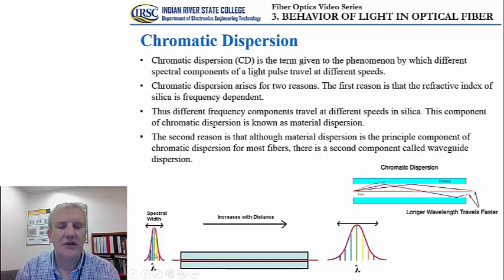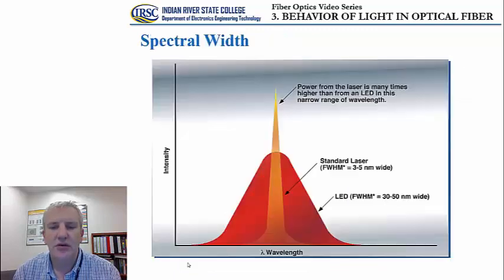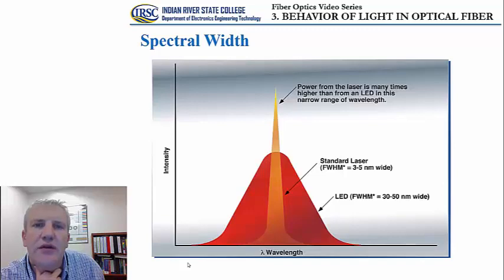And we see that each of these different wavelengths will be propagating along the core of the optical fiber at different velocities, thus causing the time delays on the other side of the optical fiber and ultimately spread of the pulse.